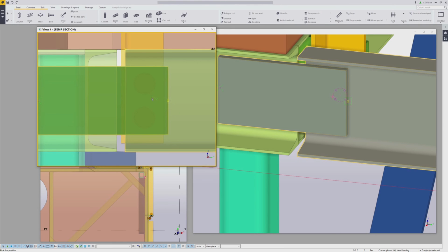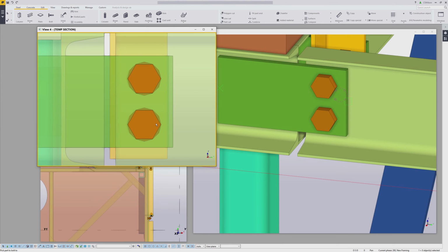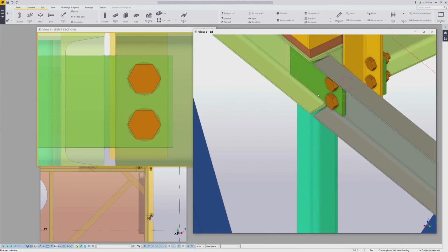And for our first position, we're going to give a control point at the midpoint of the plate at the end here. Control point, we're going to come in 1.25 inches and give another control point. We're going to go straight up with our ortho on 1 inch and give the first point. And we're going to come down 2 inches with our ortho on perpendicular and give another point.